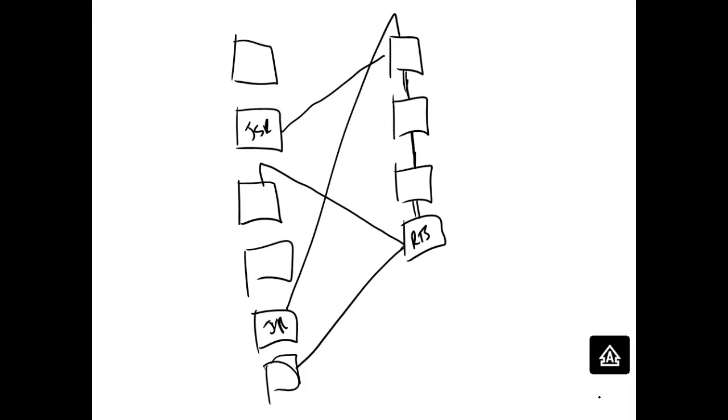And it will always come back to the next rung after the jump instruction. Jump subroutine. So it automatically remembers where it is. It uses something called a stack, which we'll talk about later.